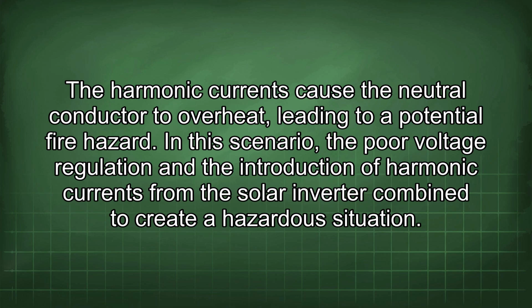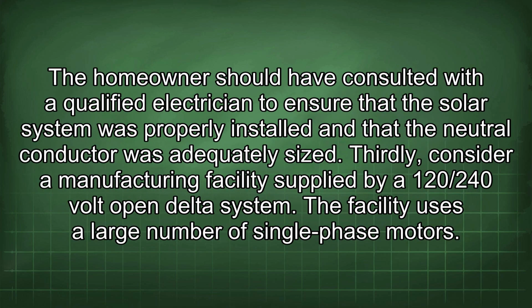In this scenario, the poor voltage regulation and the introduction of harmonic currents from the solar inverter combined to create a hazardous situation. The homeowner should have consulted with a qualified electrician to ensure that the solar system was properly installed and that the neutral conductor was adequately sized.